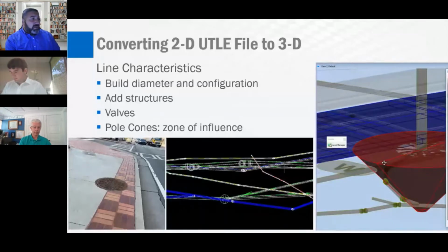One step involved is creating a 3D utility model, using metadata that we input into our 3D modeling software, such as Bentley OpenRoads, which all of the slides we're putting together have been created in. Software such as Bentley OpenRoads helps us call out specific details pertaining to how our utility line work is depicted. For creating a 3D utility model, this would be items such as internal and external diameter or dimensions of a utility, the minimum depth of cover, which we'll take from our state's utility accommodation policy, and the level in which the utility line work resides.